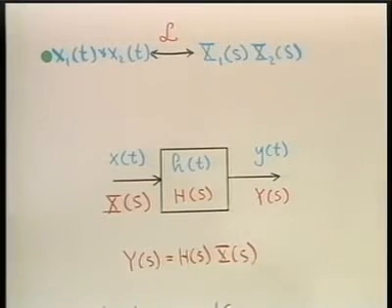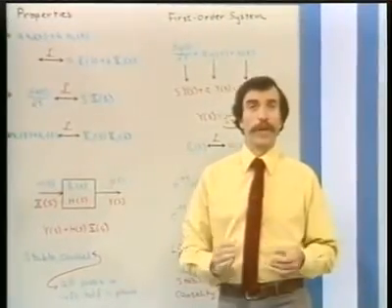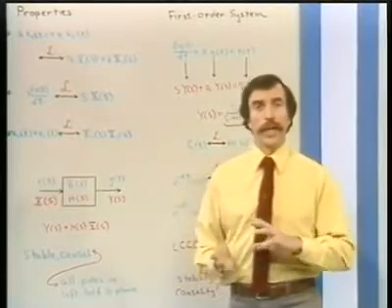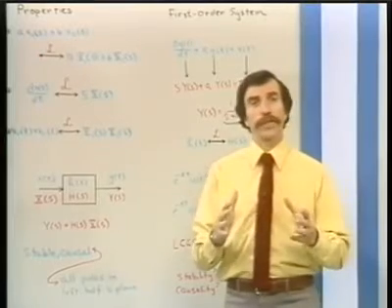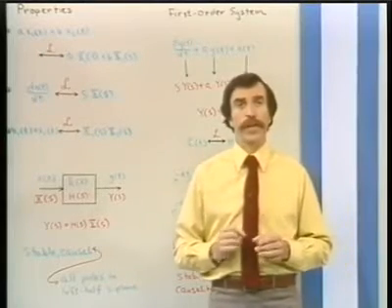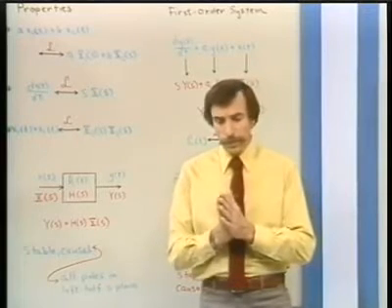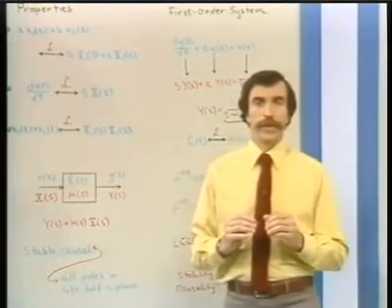And again, this, of course, is a generalization of the corresponding property for Fourier transforms. In the case of the Fourier transform, the Fourier transform of the impulse response we refer to as the frequency response. In the more general case with Laplace transforms, it's typical to refer to the Laplace transform of the impulse response as the system function. Now, in talking about the system function,